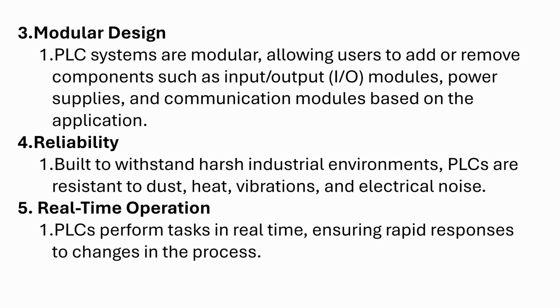PLCs are very reliable. They're meant to be in harsh industrial environments. They're pretty resistant to dust, heat, vibrations, and even electrical noise. Also, PLCs can perform tasks in real time, which ensures that you have rapid responses. If you've got a process that's changing rapidly, you need a controller that can keep up with that.